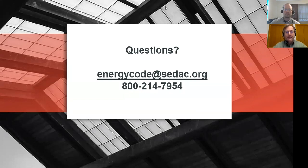All right, we're going to end our polling on this question real quick. For question 1, what is required for exterior lighting control? Looks like we've picked up on, yes, we do need a timer or occupant sensing controls, and we need daylight controls. Excellent. People picked up on that.